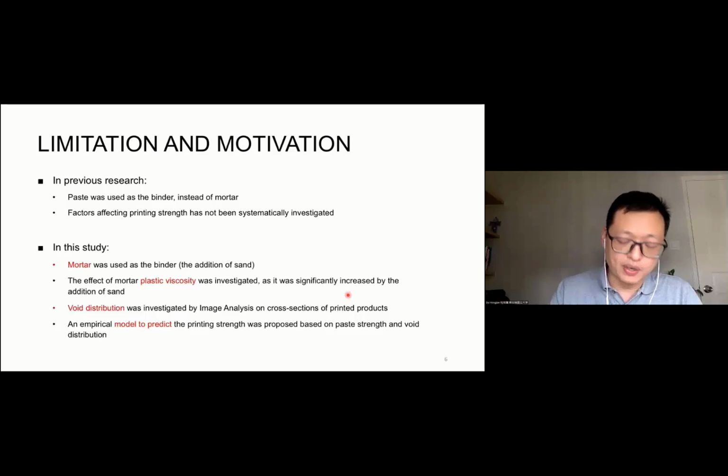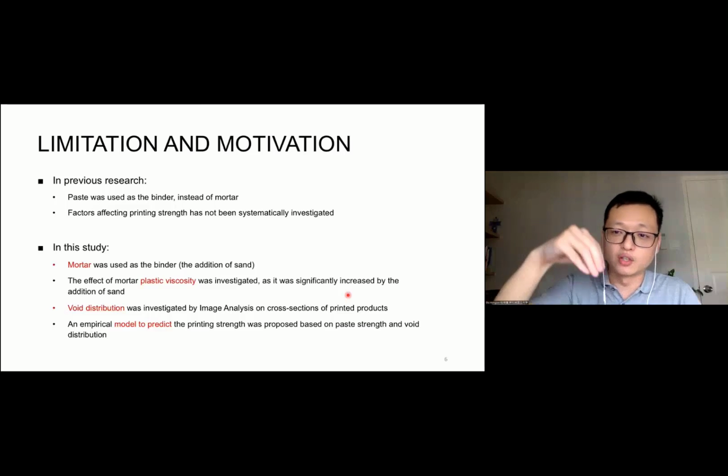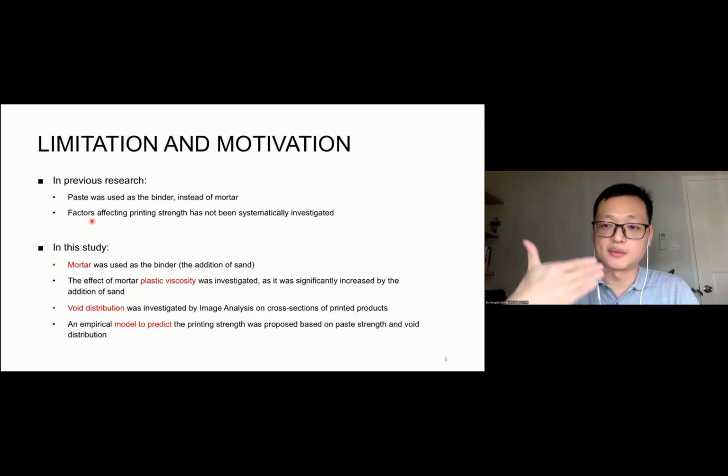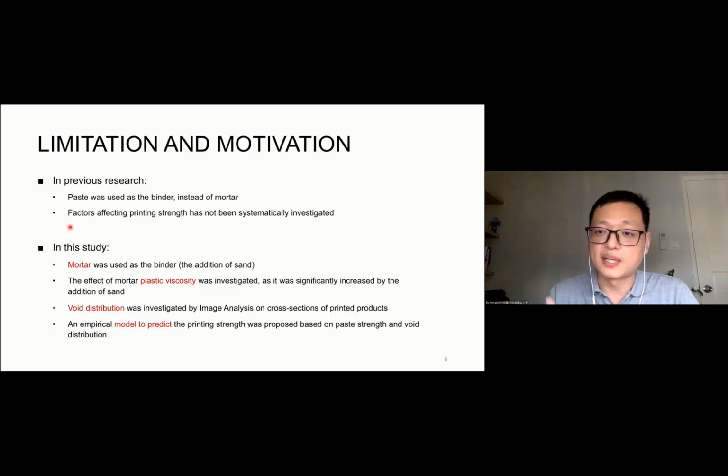However, based on our previous work, we have some limitations. The number one limitation is that we only print cement paste from the feeder to the nozzle to the aggregate bed. Secondly, in our previous work, we only investigated one specific cement paste as the ink. There are many other factors that may affect the performance of 3D printed aggregates, such as the viscosity and the water to cement ratio. If we want to include sand, how will the sand affect the printed product? So today I want to mainly discuss a few parameters.